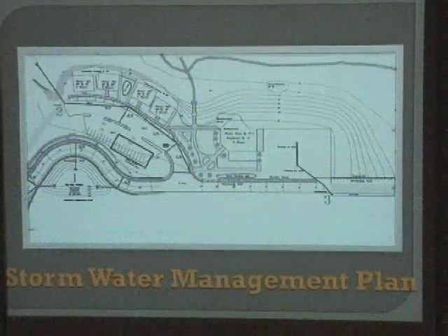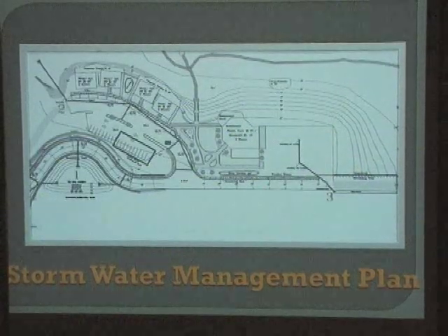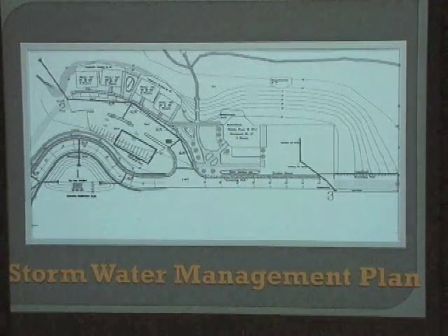Hello, I worked on the site civil engineering team, and this is our stormwater management plan. We had two main design concerns. One was to remove all pollutants from road runoff, and two, to allow for some groundwater recharge. We broke our site into 3 sections, each designed to hold around the same capacity.